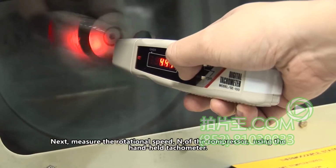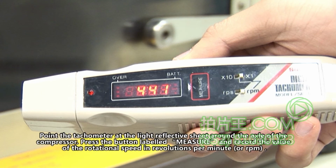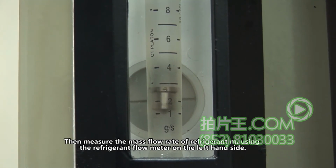Next, measure the rotational speed N of the compressor using the handheld tachometer. Point the tachometer at the light reflector sheet around the axle of the compressor. Press the button labelled Measure and record the value of the rotational speed in revolutions per minute, or RPM. Then measure the mass flow rate of refrigerant, MR, using the refrigerant flow meter on the left hand side.